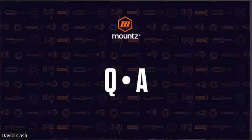All right. Next question we had, Dave, is when you're using a torque analyzer in a verification process, is there a certain mode that you should use for that process, or does it depend on the tool type? So it's going to depend on the actual tool that you're using. In most cases, you'd want to use the peak mode. There are typically 3 different modes that are mostly used. A peak, which is going to measure the highest torque delivered.